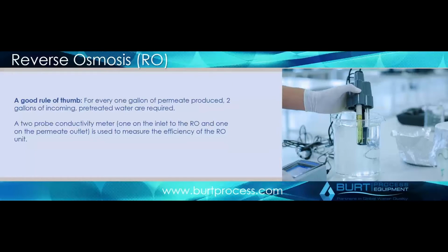So when you see an RO that's rated for 3 GPM at 70 degrees Fahrenheit, if that water is now 50, that RO probably runs at 2.5 or 2.2 GPM. Not a huge difference when you're talking about a smaller RO. You get to 20 or 50 GPM ROs, and now you're talking about a 10 or 15 GPM difference in flow through it. But you're also now talking about a lot more downstream requirement for treatment in those cases.